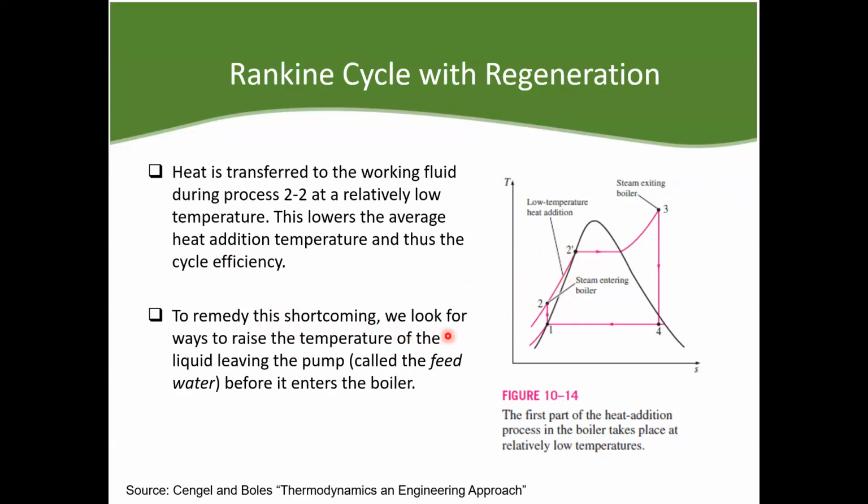To remedy this shortcoming, we have to raise the temperature at this step, the step wherein the liquid leaves the pump. And we call it the feed water heating. Okay, so before entering the boiler here, we try to raise the temperature at this point. So that when it enters the boiler, mataas na yung temperature and thus increasing the cycle efficiency. And that's called the feed water heating.